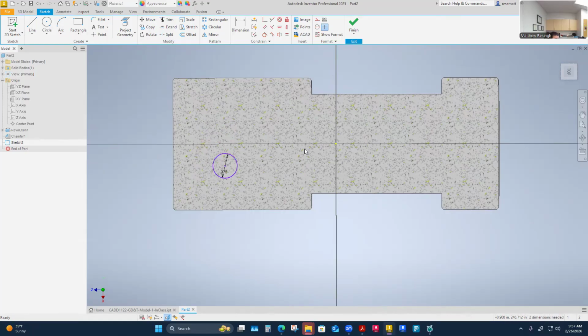Well, I'm just going to constrain it to some projected geometry down the middle. So I'm going to say project. I can either choose this plane to project, which looks like a line in this view, or I could choose this axis here that's going to be the Z axis as well. So either one, they're kind of doing the same thing. I might choose the axis here. There's my projected axis. Oh yeah, it's the Z axis, if you have your part oriented like mine does. If I'm looking to do more projected geometry, it's pretty common for me to just hover over them to determine which one I want. But I feel like you could choose a plane here, this plane, or this axis here.